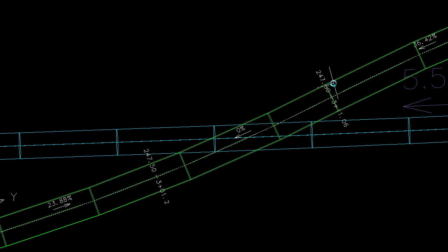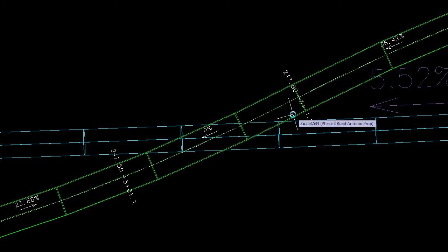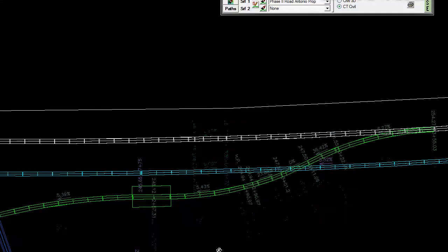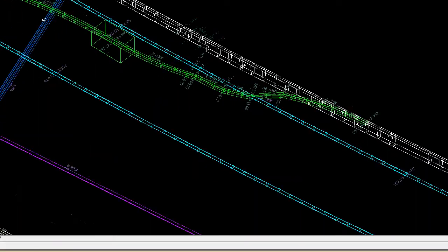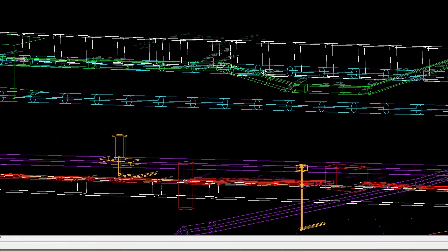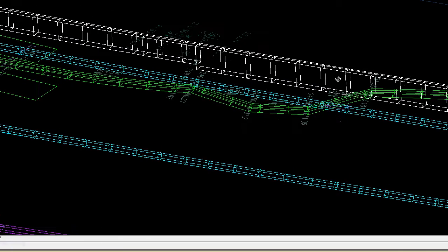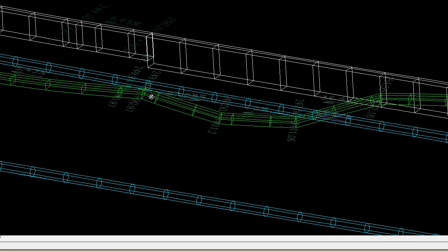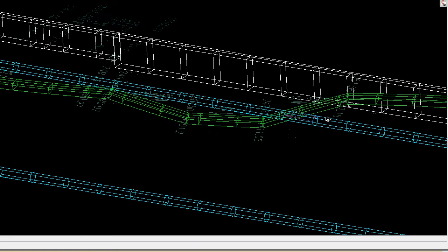Pretty ugly, huh? Little bump there. But you can see what happened here. I took the profile that used to go straight through here, told it to hold that point, add a point here and here that's 1 foot below, and this was already a PVI, so I just let that one stay. And now it goes underneath. Again, looking at this ain't reality, so I'm not happy with this. So I'm going to edit this guy.